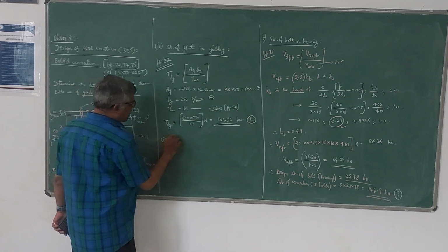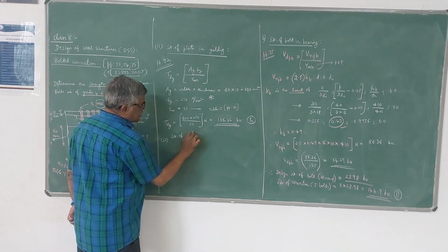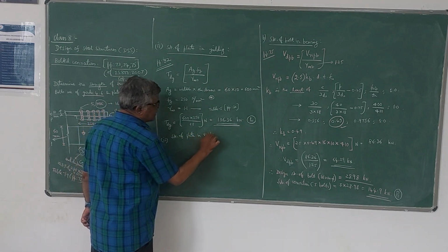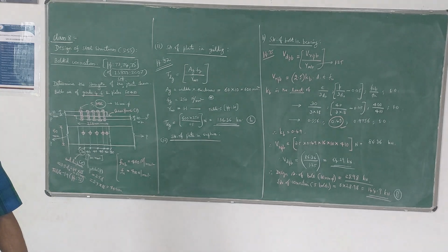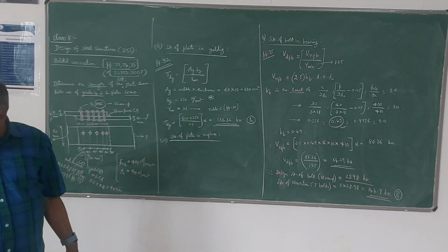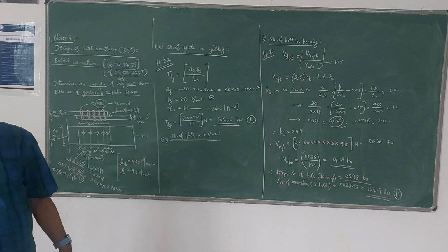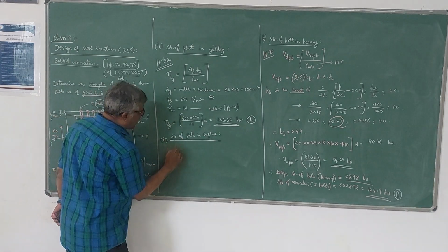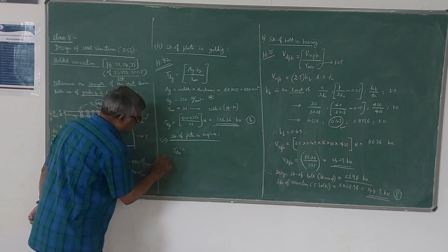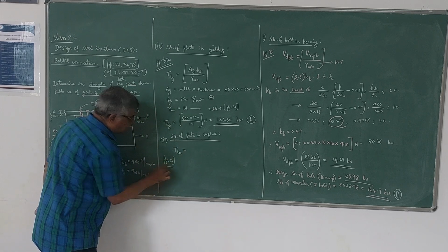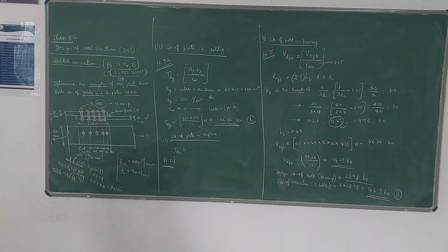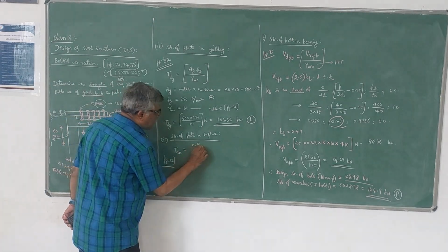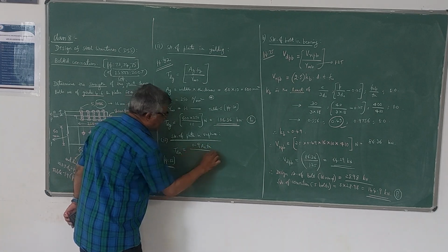Okay, next, the third value is the strength of the plate in rupture, which considers the net sectional area An. So that An we have to calculate now. The net area of the section we have to calculate. The formula is on the same page 32. So Tdn is equal to, for the plate, the design strength 0.9 An Fu by gamma m1.